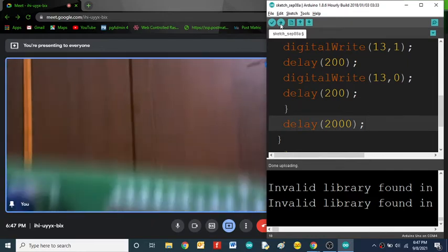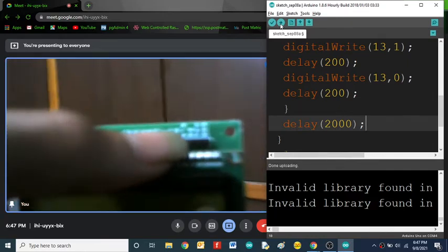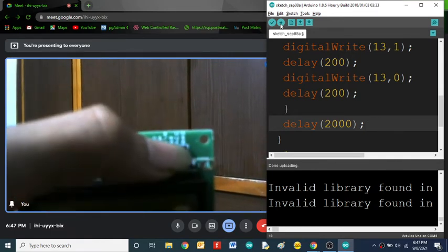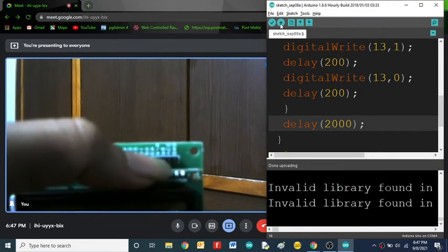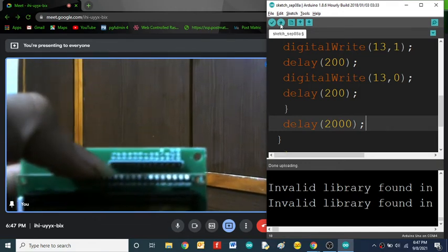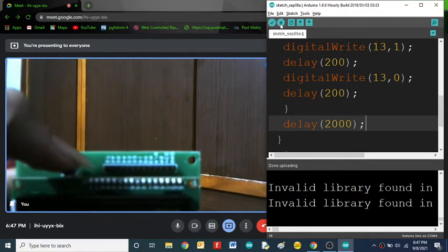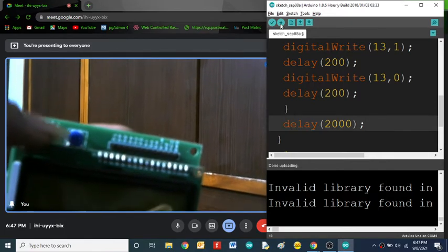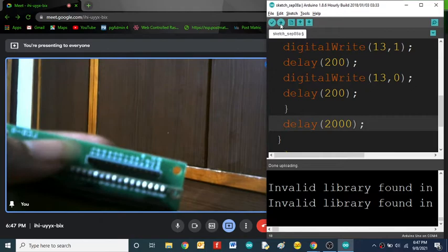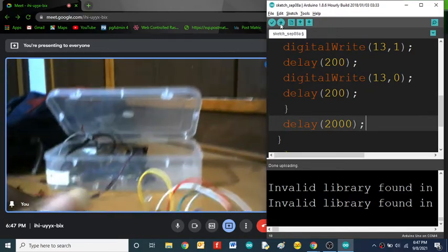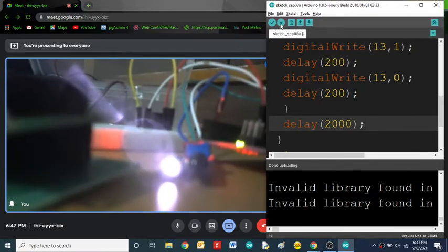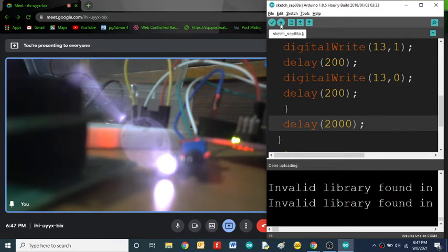Now connect. Your LCD has 16 pins, like we discussed in the previous classes. The first pin is ground, the second pin is VCC, then RS, RW, enable, and D0 to D7. The anode and cathode are internally short circuited, and the contrast pin is also given here. Using this potentiometer we can vary the brightness. Now I will make the connection. Take jumper wires called male to female.